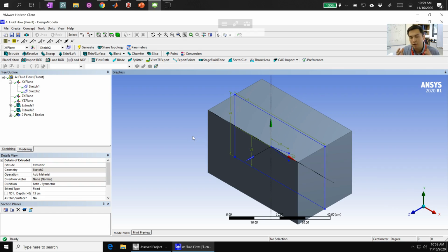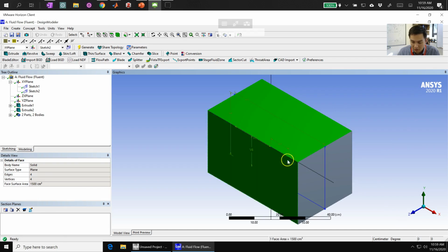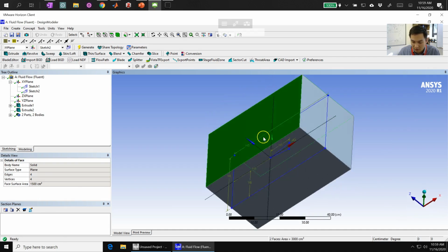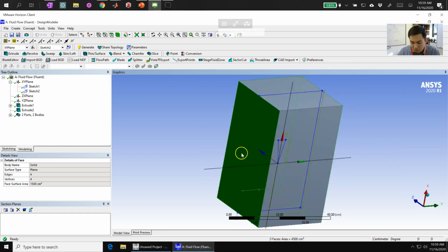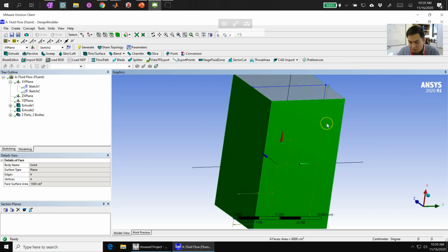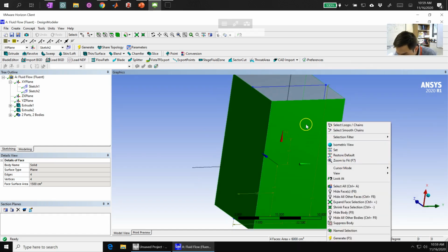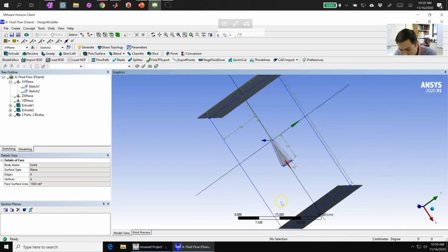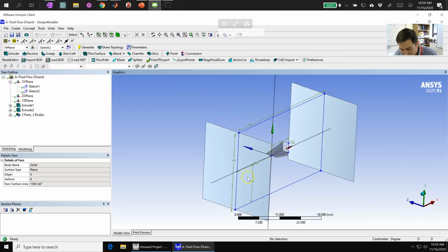So now one of the challenges that you're going to be facing as we go through the rest of the geometry part in the mesh is that sometimes we can't see the wedge. And so in cases where we want to see the wedge, we're going to have to hide some of our faces. So I'm going to start doing an example of this. I'm going to click on the top face, and I'm going to highlight each of the side faces. Right click, and we have the option here, hide faces. So that hides those 4 faces, and now I can see my wedge again.